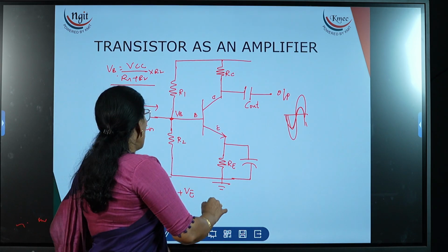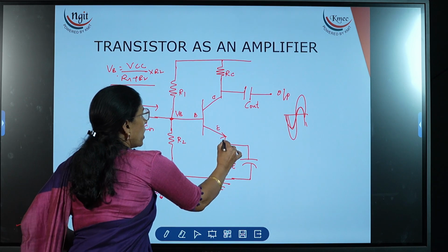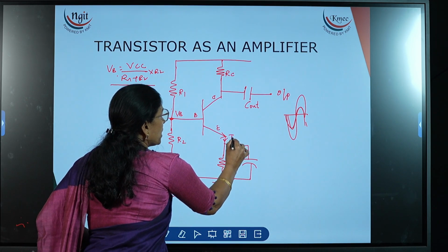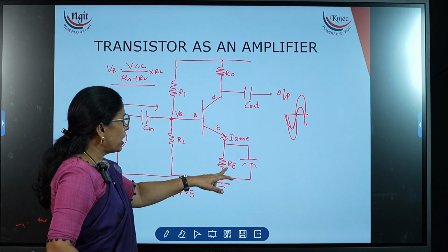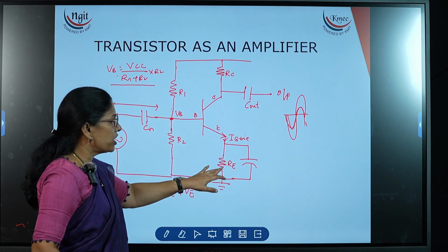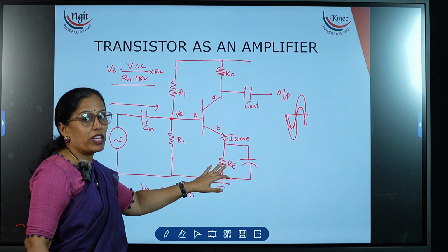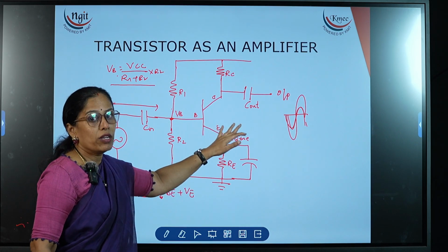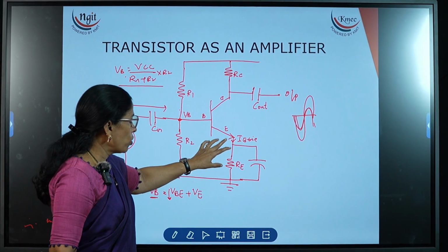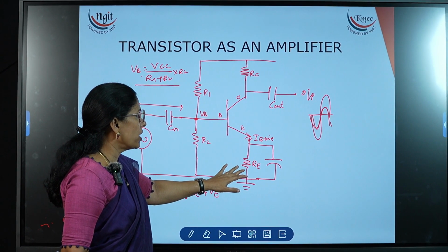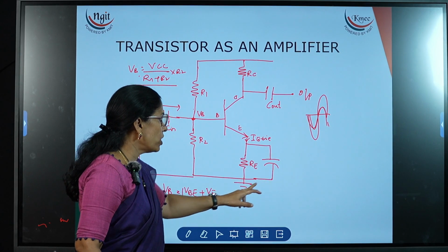Now after connecting the AC, if both AC and DC currents are flowing, then along with the DC, if AC current is also flowing, the drop will increase, thereby the overall gain will reduce. That should not happen. It means only DC current should flow through the RE and AC current should flow through the CE.